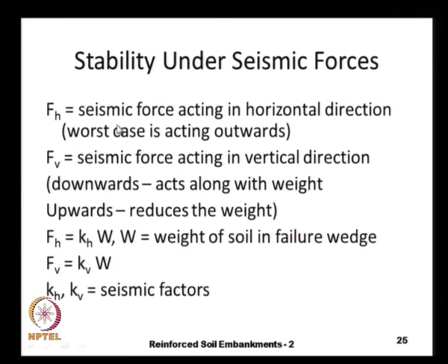because if it is acting into the soil, it tends to stabilize the soil. And Fv is the seismic force acting in the vertical direction, and it could act either downward or upward, because it can act both ways. If it acts downwards, it acts along with the weight of the soil. So, it increases the normal resistance, but then also increases the shear force, and if it acts upwards, it reduces the weight.